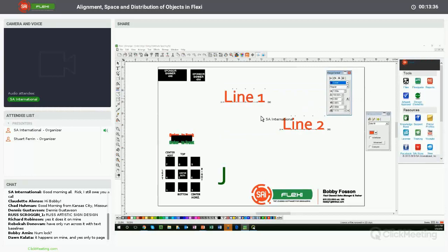But if I want them to be perfectly level, depending on the font, sometimes it's not always easy to line them up. And aligning to the bottom or aligning to the top may not work. For example, let's say I have a lowercase g. Well, line bottom won't work. If I have, in this case, a capital L. Well, if I change this to a capital S, it's got a slightly rounded top, which normally goes above the top line, so it's not going to match either.